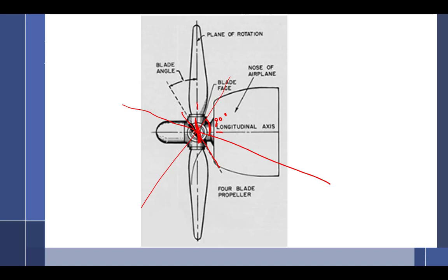And we'll talk about the protractors that we use. But basically what you're going to do is put a protractor on a surface, and you're going to zero it out. And you're going to say that's 0. And then you take that same protractor and put it against the blade. And it'll tell you the degrees because you zeroed it out on the longitudinal axis.